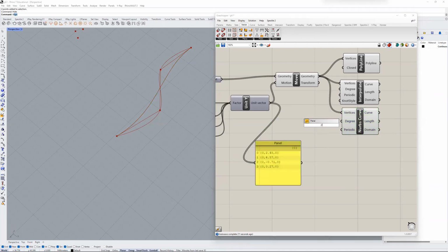If I set the degree, with a panel, I can also use a number slider. Maybe a number slider would be easier. So I want to create a number slider. 0 is my minimum. I want it to be only integers, so I don't add any decimals. And then my maximum, let's say 5, just to show. Realistically, 3 is the maximum you want for degree, but I digress.